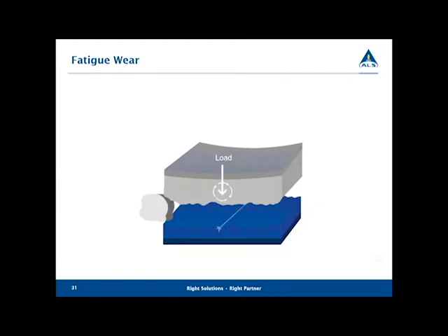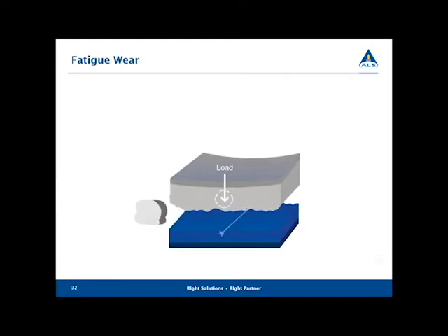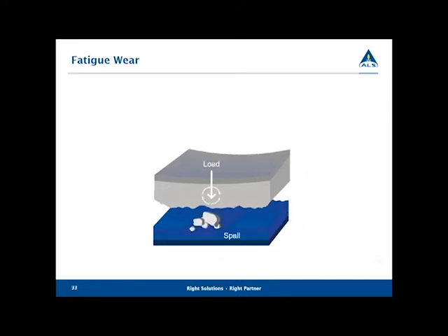And when it does so, you set up a microcrack. And when that microcrack occurs, it grows bigger and bigger, it propagates. It starts compromising one of the componentry, if not both. And when that happens, we actually develop a spall. And as that spall develops, we start getting parts coming off as well, which then lead to more types of wear debris and so forth. So it's just a situation that accumulates.